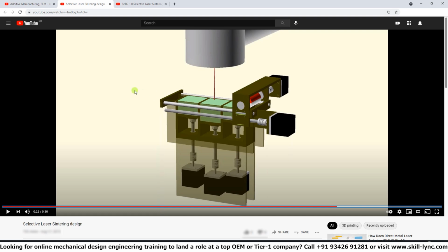So another advantage that we discussed is that using selective laser sintering or selective laser melting, you would not need support structures to support your model. However, you do need to take into account that when melting this, if you create an enclosed surface such as a sphere, that sphere would be filled with metal powder.